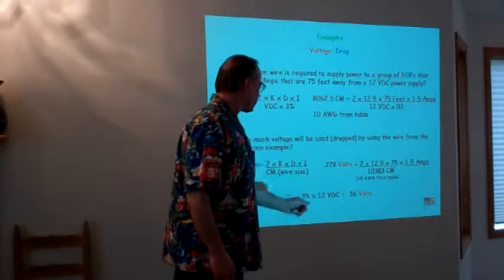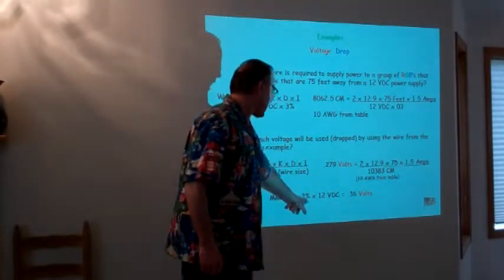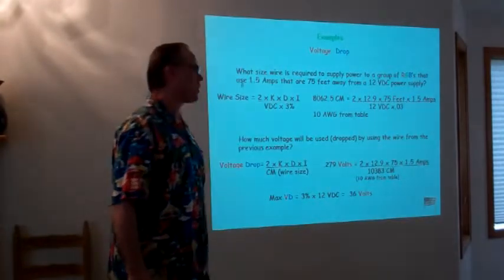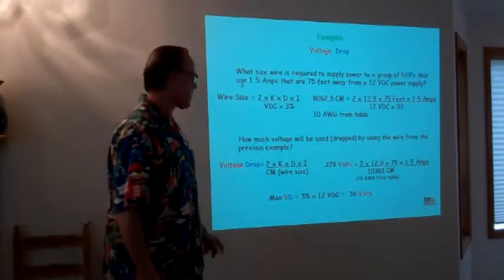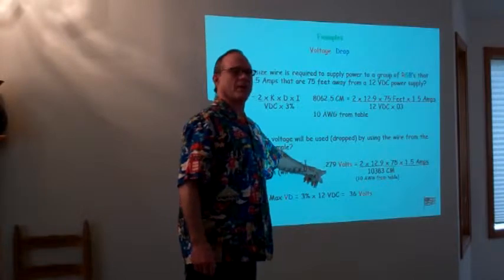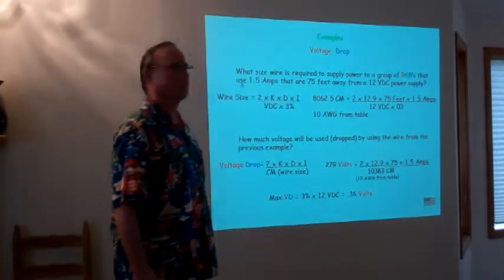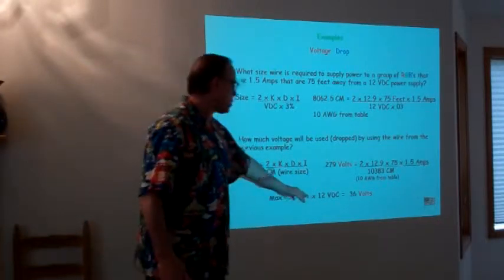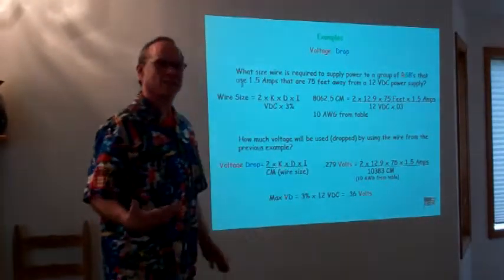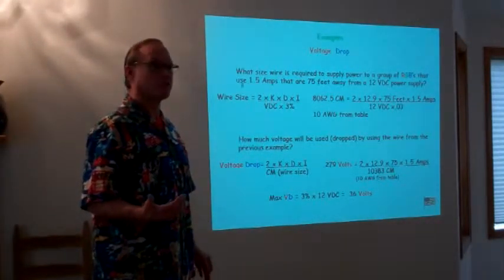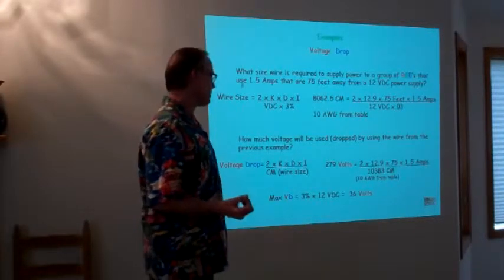Well, 0.279, well, we remember that we don't want to exceed more than a 0.36 voltage drop. We're well within that. Okay, that's the maximum, 0.36. We're at 0.279, so we're well below our 3%. We're less than 3% variation, which means our circuit is going to be fairly effective at that point.